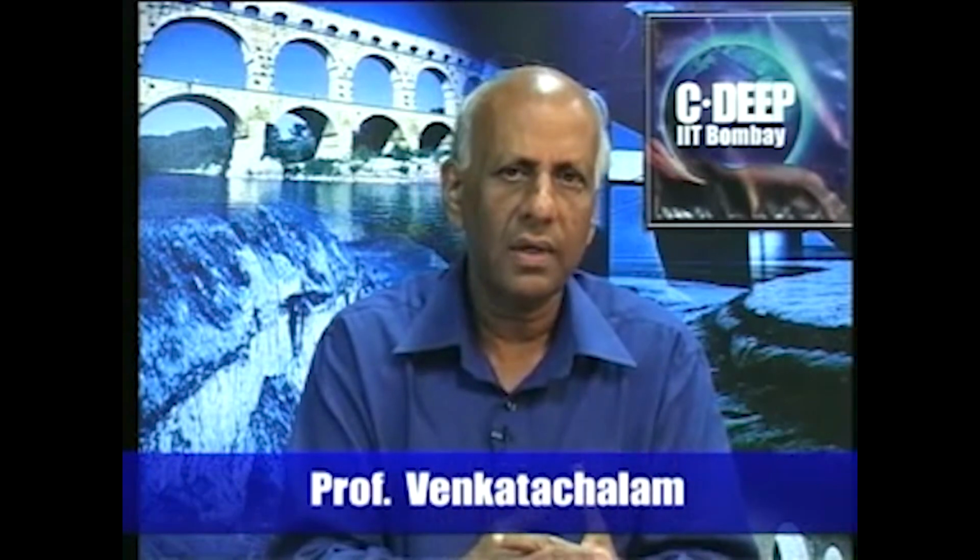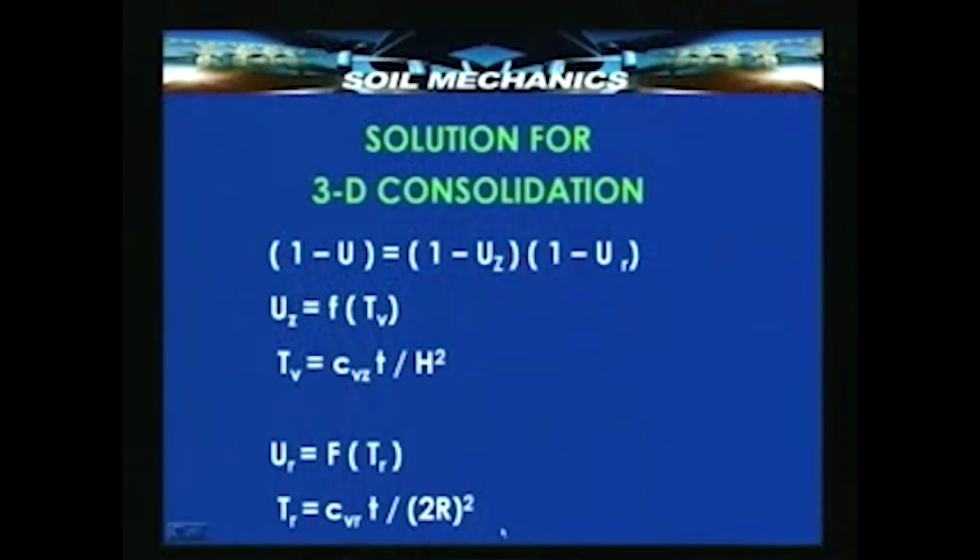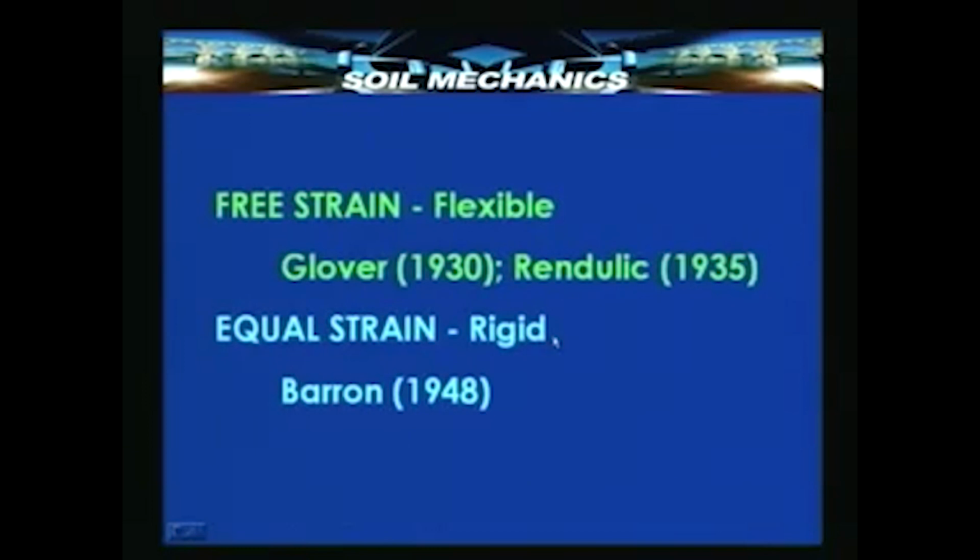Right now, as a prelude to that, we are simply seeing how 3-dimensional consolidation can be split up into consolidation in the vertical direction and consolidation in the radial direction, and they can be put together to get the time factor for the vertical direction and the time factor for the radial direction. Now, if we know how to determine the time factor for the vertical and the radial directions, we can get the degrees of consolidation for the vertical and radial direction, from which we can get the total degree of 3-dimensional consolidation. Okay. Let us see the next one.